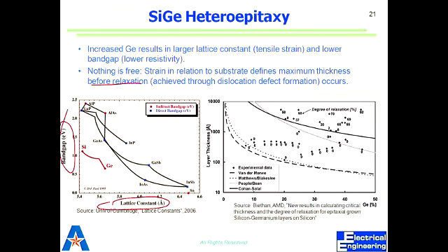No, you don't break down the oxide, but that's your switching voltage. Yeah. Above which you are on, below which you are off. So in a transistor, you want that to be very clearly defined, so you have the switching effect, right? Up or down. In the case of a diode, it's just rectification. You want it to work in one direction, not the other direction. In the other direction, you can go to a certain voltage and then it breaks down. So that's a different concept of breakdown. In that case, it's different.